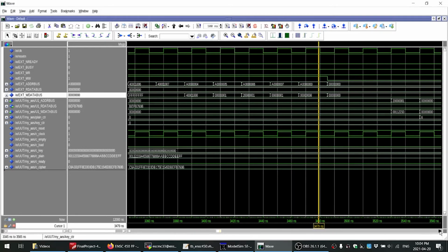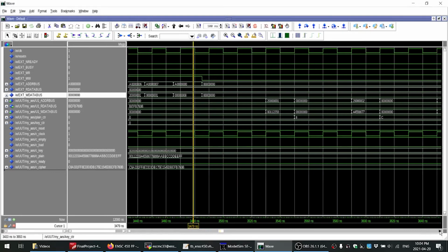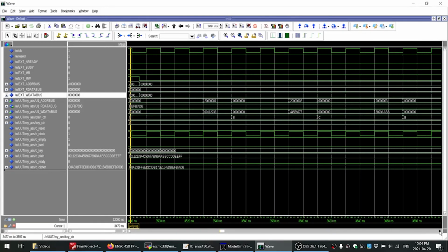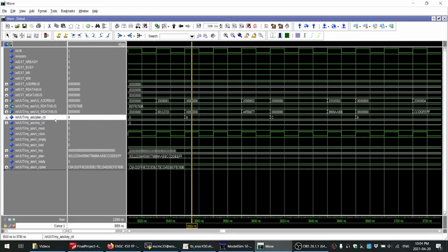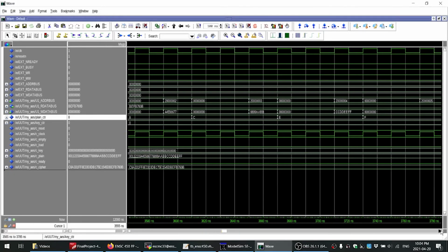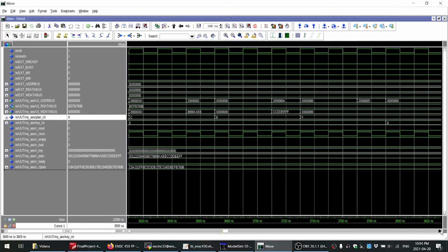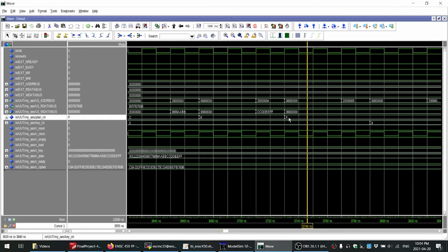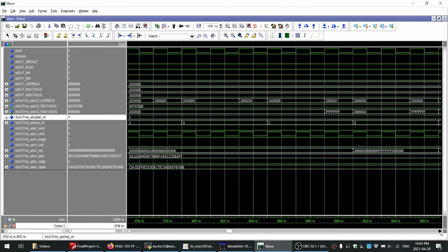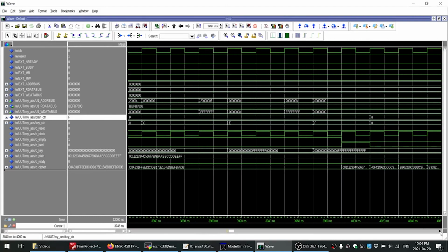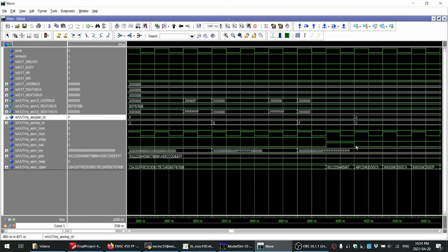And those transfers are taking place here, as we can see. The plain text counter of the AES core buffer is counting up all the way. It reaches the value 16 when we know all the bits of the plain text have been received. And the same thing happens for the key input bits.